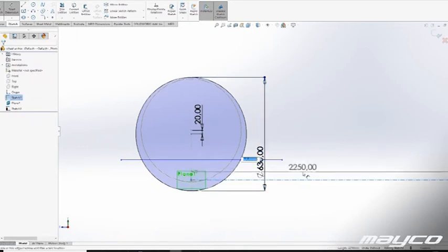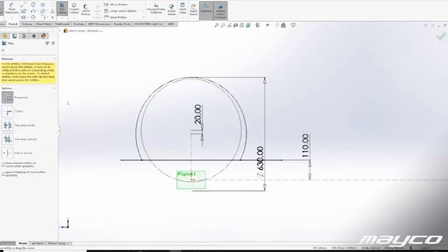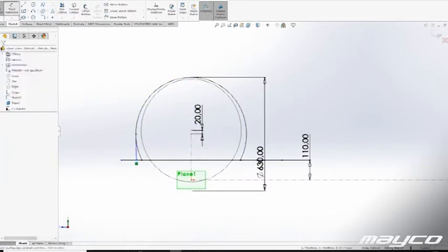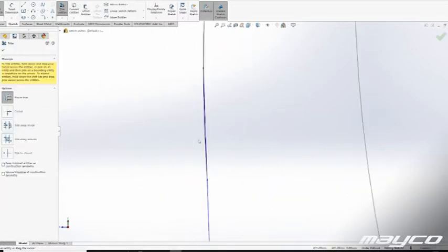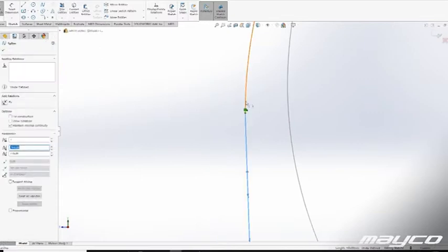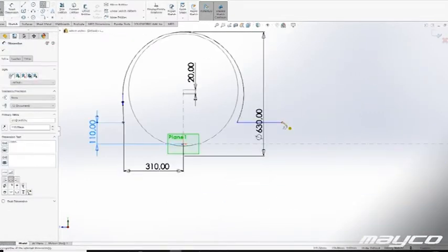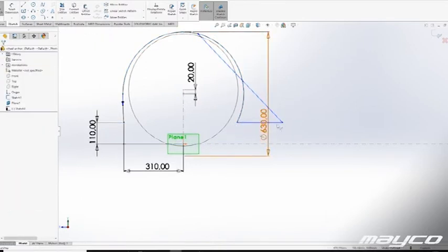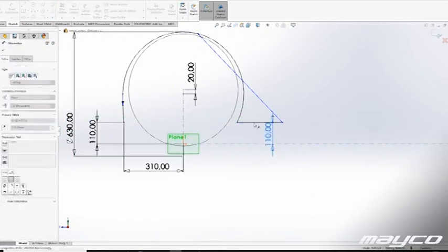First off, I have the wheelbase of the car and I know the rim diameter or the tire size basically. And the next step is that when I draw in my tire size, I keep in mind that the tire will sink into the pavement a little bit due to compression. So the center of the wheel will be a little bit lower than if you would draw it with the tire meeting the surface exactly.